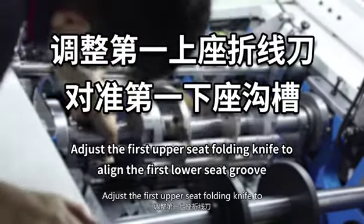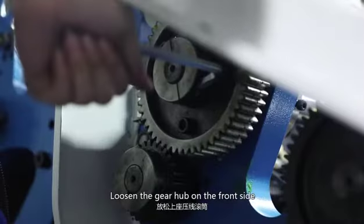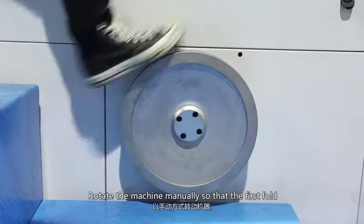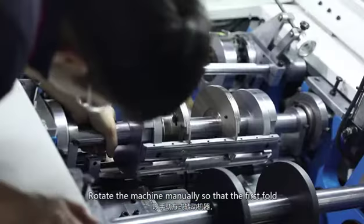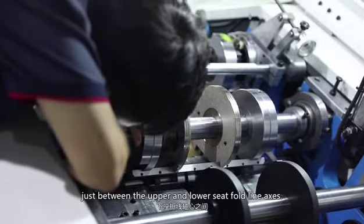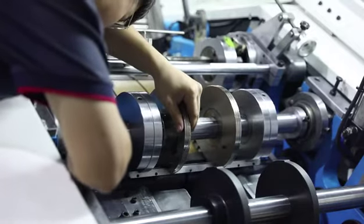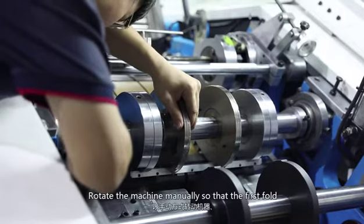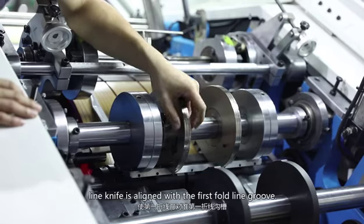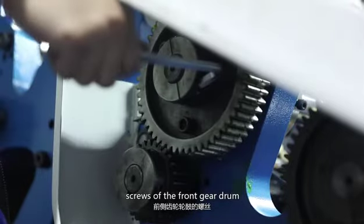Adjust the first upper seat folding knife to align with the first lower seat groove. Loosen the gear hub on the front side of the upper seat crimping drum. Rotate the machine manually so that the first fold line module of the lower seat crimping roller is just between the upper and lower seat fold line axes. Rotate the machine manually so that the first fold line knife is aligned with the first fold line groove. Keep the position still and tighten the screws of the front gear drum.